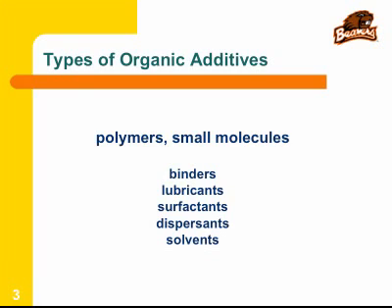Also, if you have a die cavity to make a shape, the die itself will get abraded by the motion of the powder against the wall. So you need some lubricants to be able to reduce the wear and to reduce the friction between the powder and powder surface so that particles can slide across more easily. The more easily they can slide past each other, the higher the density of the part at any given pressure.